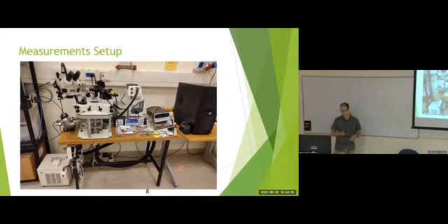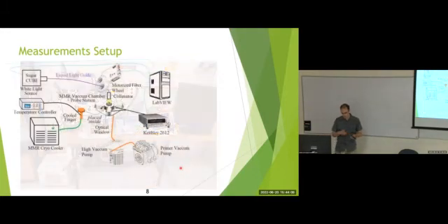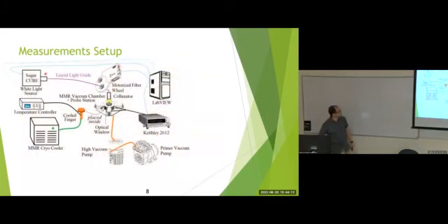So this is the measurement system I assembled. Everything is controlled by the computer here. We have the white light source and the motorized filter wheel. Together, they form a light source with 6 orders of magnitude of illumination up to 10 solar intensities. And we also control the temperature in the range of 100 to 300 kelvins. We control this Keithley, which forces bias on our devices while measuring their current. And all this probe station is evacuated by this primary and turbo pumps.